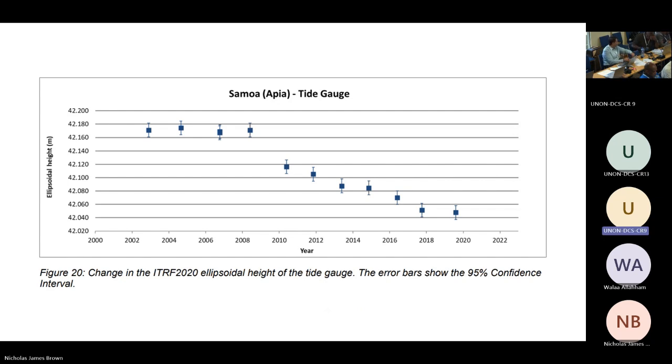For the offshore, we use GPS and also the SBASs. We use the mean sea level, you level from land, tie that to your benchmark, and then it goes all the way. We use the tidal datums.